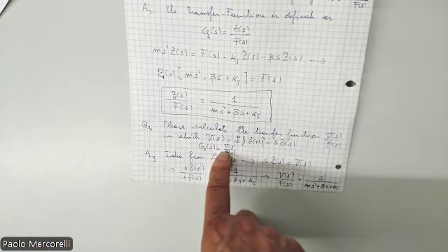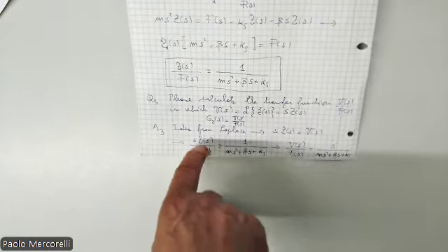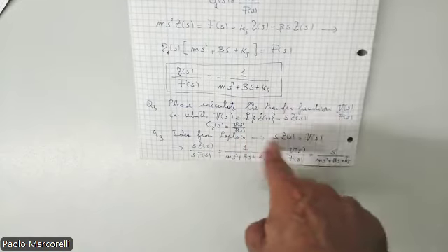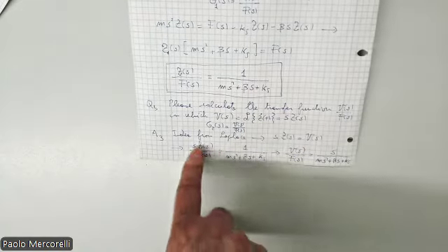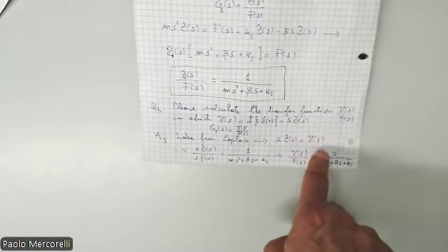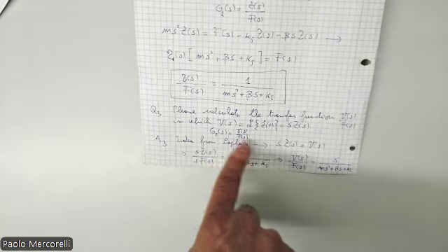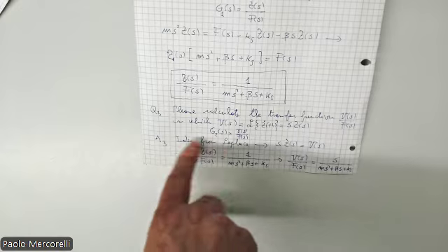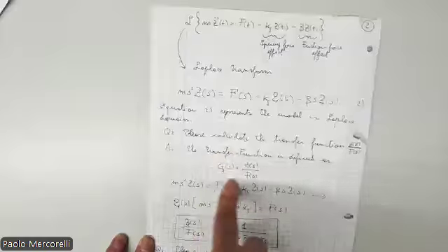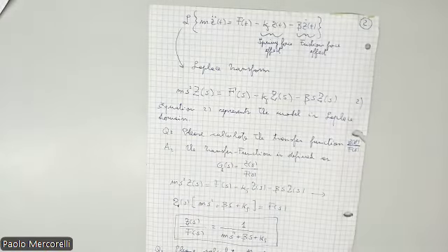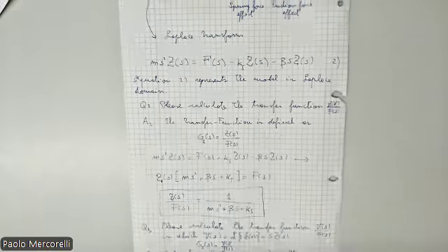This was the question, because it is enough to apply exactly the derivative theorem, because S multiplied by Z equals V. S multiplied by Z capitalized, to be precise, equals V capitalized. This means if I multiply my original G1 by S in numerator and denominator, I didn't change anything.